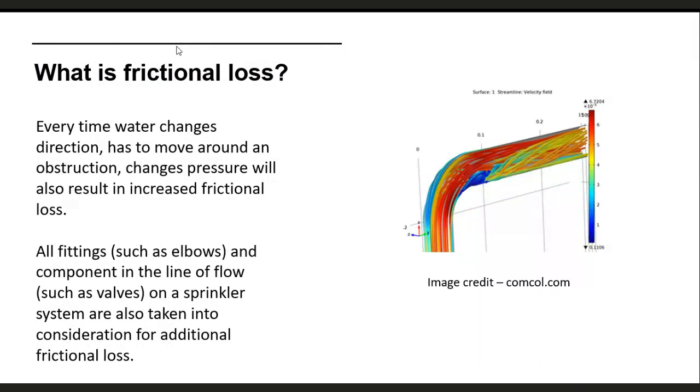As soon as we're not doing that, then we're creating additional movement in the water, and again, that's going to cause additional frictional loss. And this is all very, very complicated as far as actually understanding and calculating exactly what is going on the inside of a pipe.